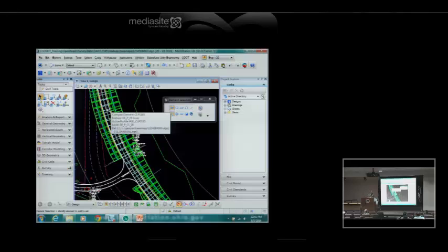It can all be in as few files as you want, although ODOT does require a base map for survey and a base map for design information, and right-of-way is also a requirement in the CAD manual. So there's really only 3 different design files that are required. Everything else is just how you want to work. So I've got it split up just because I can. On a small project, it may make sense to keep the center line and the superelevation and the corridor all in one file, but I've kind of split them up. So I'm actually in a 2D file here, and I'm working in 2D from the design part of OpenRoads, and I'm going to back up and talk about survey quite a bit this afternoon.